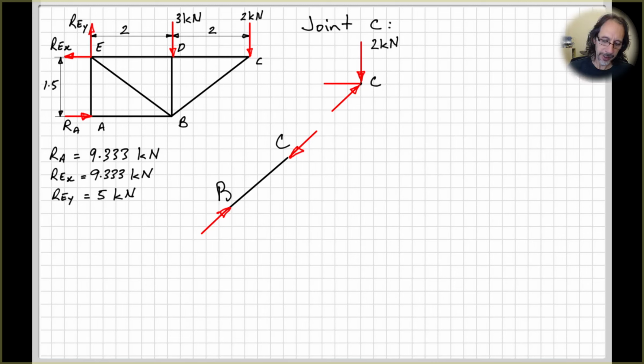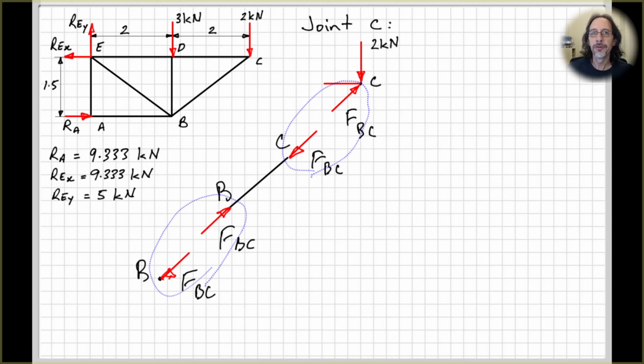And then if we go further and look at the joint at B, and we'll do this in the coming pages in the rest of the solution when we need to do a free body diagram of joint B. So at each connection, we have equal and opposite action-reaction pairs. So we're obeying Newton's third law at these locations where we've imagined that we've separated the truss member from the pin joint. So these forces here must be shown equal and opposite to each other.